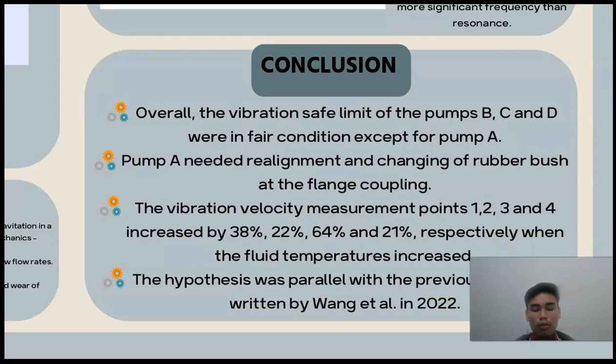For the effect of temperature fluid to the vibration, velocity measurement points 1, 2, 3, and 4 increased by 38%, 22%, 64%, and 21% respectively when the fluid temperature increased. This hypothesis was parallel with the previous research written by Wang et al. in 2022. In this research, it showed the characteristic of the fluid does not affect the vibration spectrum characteristic.